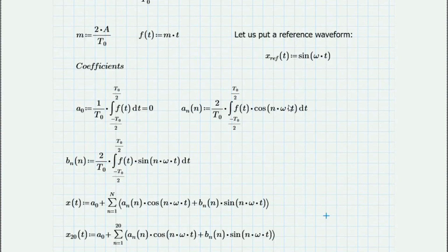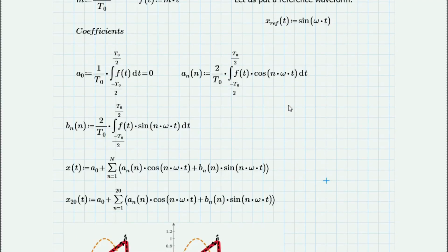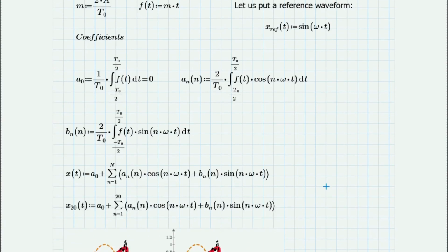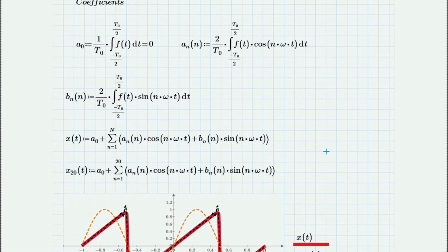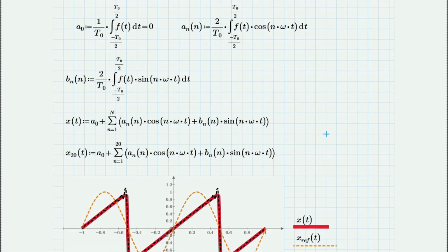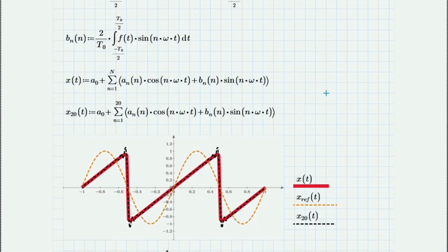The first graph displayed is the reconstruction plot. Notice how the signal begins as a simple sine wave, but as we increase the number of harmonics, the sum converges toward the sharp saw shape. You can observe the Gibbs phenomenon, those small ripples at the transition points, which is a classic signature of reconstructing discontinuous signals.